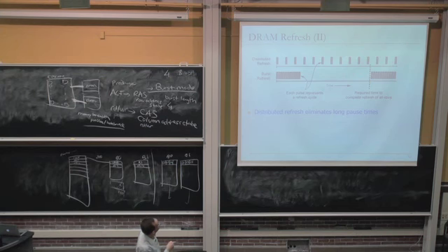Each pulse represents a refresh cycle. And there's some required time to complete the refresh of all rows every 64 milliseconds. You could do the refreshes one after another, or you could distribute the refreshes of different rows over that required time. And doing this improves your responsiveness in the memory system a lot better.